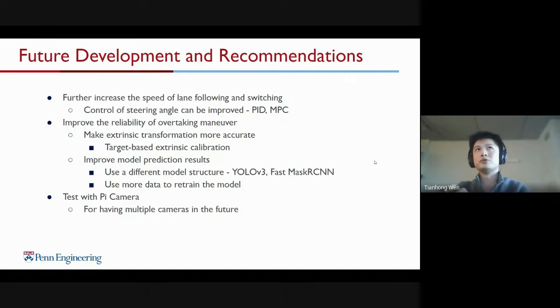So first one, to further increase the speed for lane following and switching, we should improve the control of the steering angle that we currently have. What we currently have is just a proportional gain with respect to the error, but to make the traveling path smoother, we can try to deploy PID control or more sophisticated model predictive control.